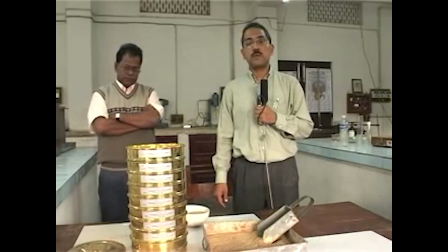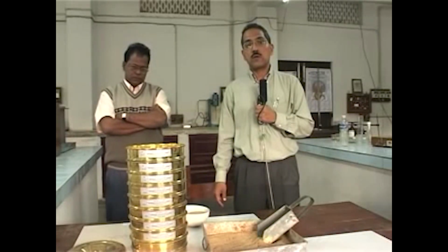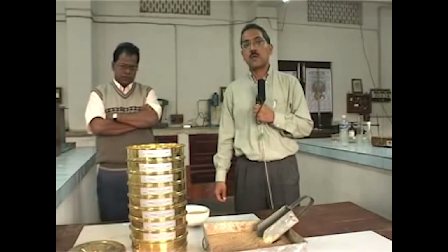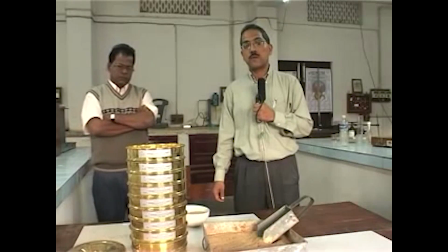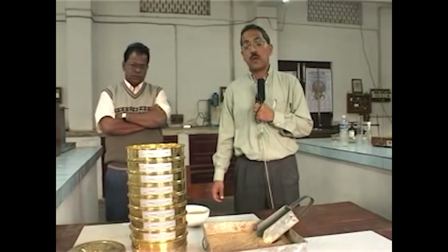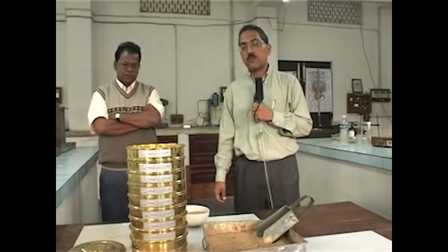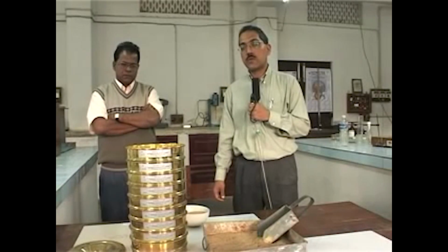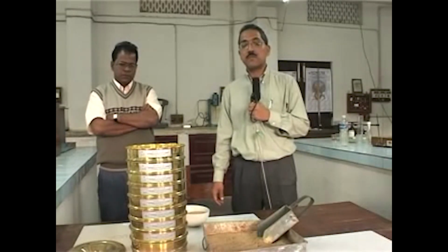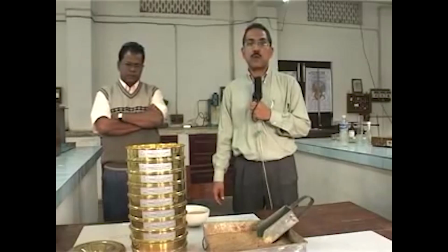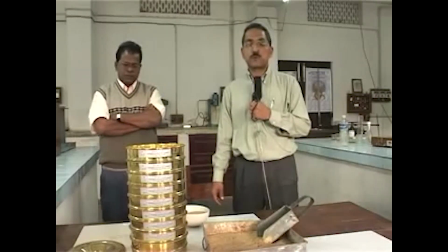Here we are going to give demonstrations of different simple laboratory tests for classification and identification of key soil parameters and rock parameters. With that said, we are going to move on to the first laboratory experiment, sieve analysis, which is carried out to find out the distribution of grain size, or the representation of different grain sizes within the soil matrix, for coarse grained soils.